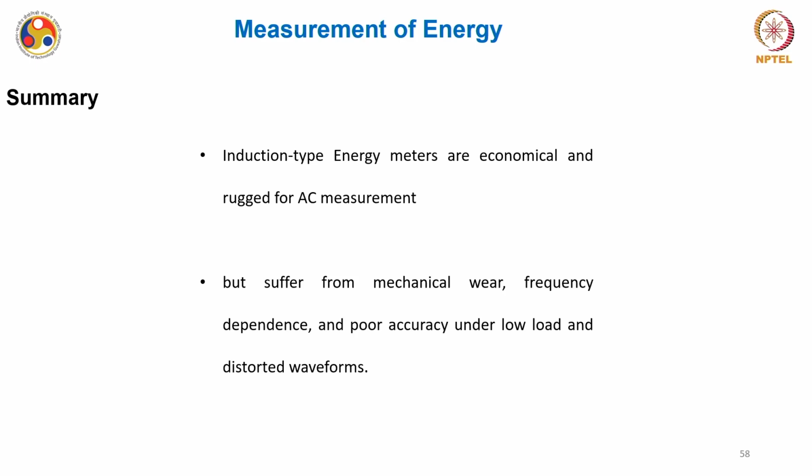However, they also suffer from mechanical wear because a disc is rotating. They are frequency dependent and have poor accuracy under low load and distorted waveform. Fine, so this is how the energy is measured.